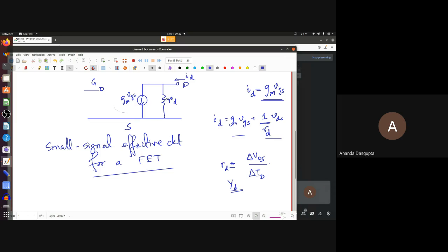In fact, it's much easier to analyze FET amplifiers than BJT amplifiers, at least comparatively. So wherever you see the FET in a small signal model, you can replace the FET with this. And very often you can make life even easier and just drop the RD, because RD is usually too big to really matter.